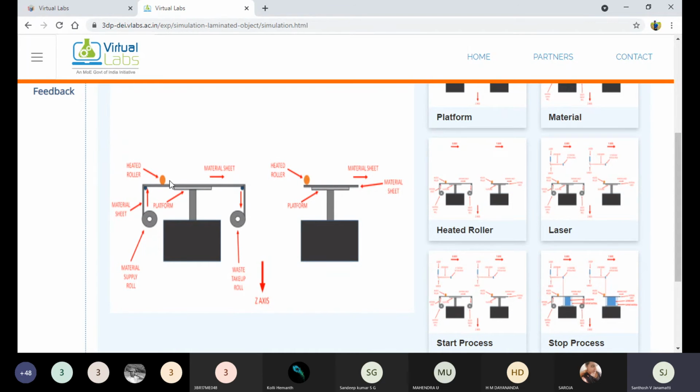That roller fuses the material and squeezes it. There may also be some contaminations present in the sheets, which may burn out. This roller also properly rolls the sheets over the platform, because sometimes there is a gap between the platform and the raw materials. Once it rolls over the work material, the material is stretched and straight, and hence we can ensure that the contact between the workpiece and the platform is close.